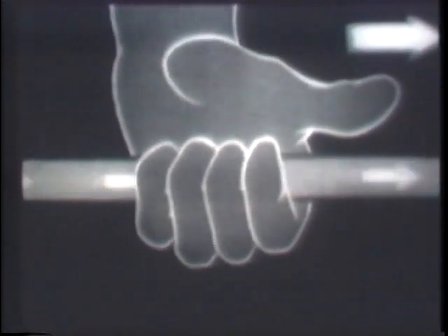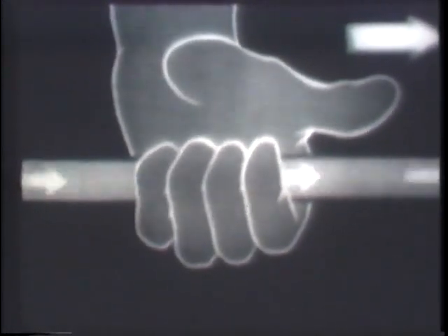The ability of the transformer to transform voltage can be understood best if we first examine an important phenomenon in electricity, the magnetic field. When electric current passes through a wire, an invisible band of magnetic force is set up around the wire. In the case of direct current, this magnetic field expands to a certain point and stays there, except, of course, it's traveling around the wire all the time. For instance, if you were to grasp the wire in your left hand and extend your thumb in the direction the current is traveling, the magnetic field will be circling the wire in the direction of your fingers.